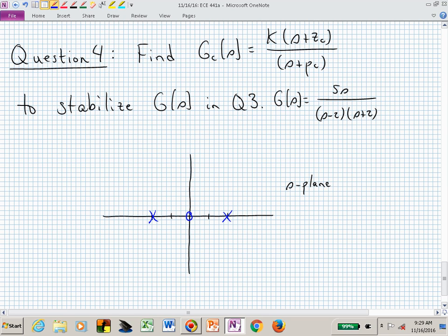And now just put one down. Don't try to think too much. Just throw one down. Put one there. And say, what happens now? And what else do I need? I need to put a 0 down. Well, I don't really. You don't always have to have a 0 to balance your pole. You do have to have a pole to balance your 0. So I could just put in a pole and change my pole-0 excess.